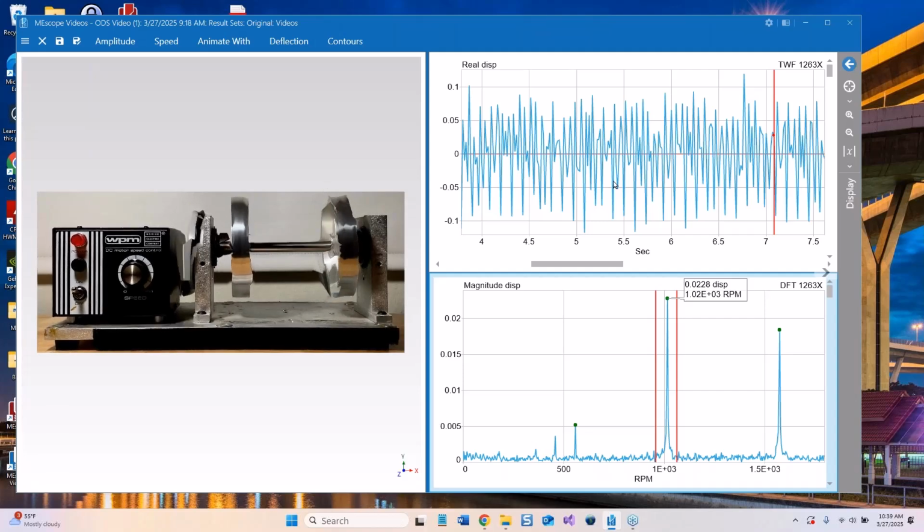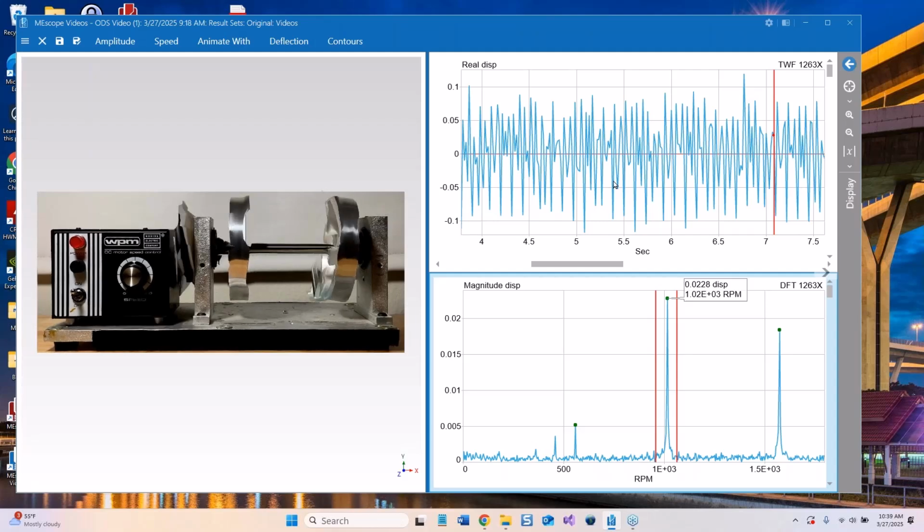spectrum-based data acquisition system has what are called anti-aliasing filters on each of the channels, and they filter out the high frequencies. There is hardware you can buy to put on the front of your phone and filter out the higher frequencies, but here there is no anti-aliasing filtering. So what we're seeing here are two of the higher orders that are aliased around half of the sample rate.